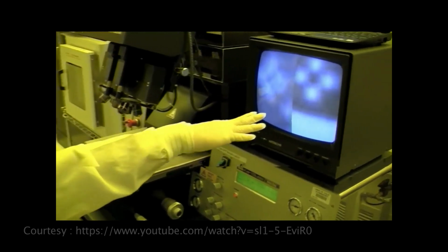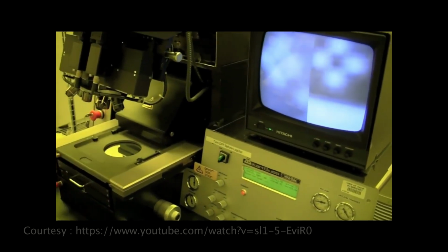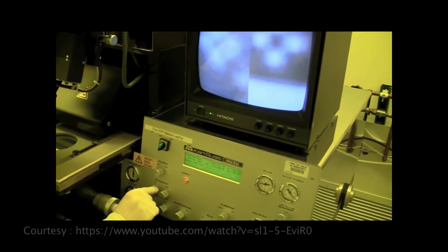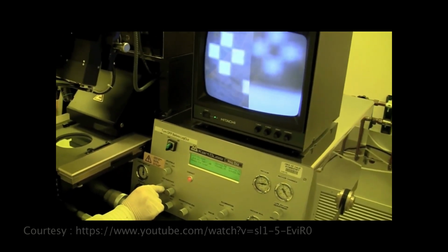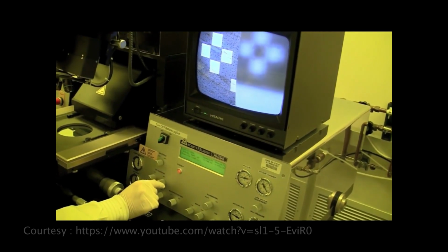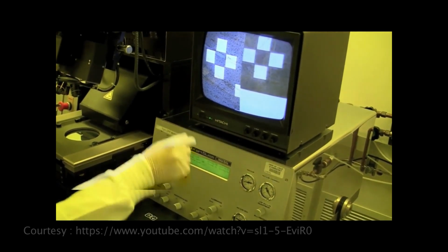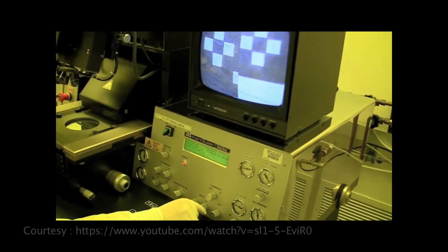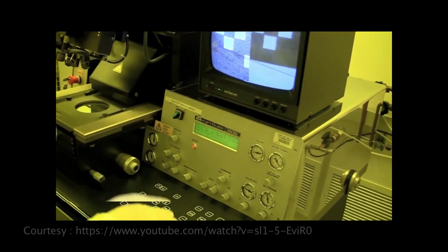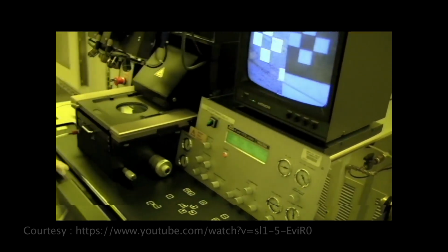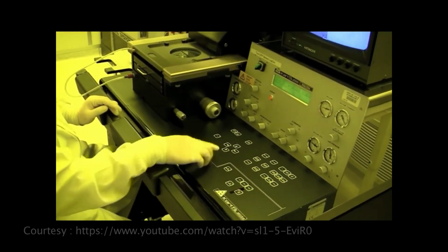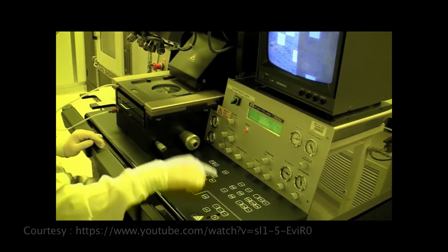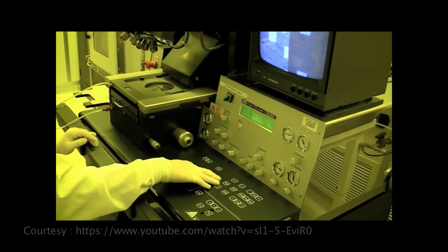It looks like we found our alignment marks on the mask. So we need to adjust the focus. So you use this top straight left and right. So the left one adjusts the left, and the right one will adjust the right focus. You can also adjust the intensity. And you can also adjust the position. So if I want to move this one up and down, I'll hit right, and then I will move it up and down. If I want to move the left one, it's a similar thing.